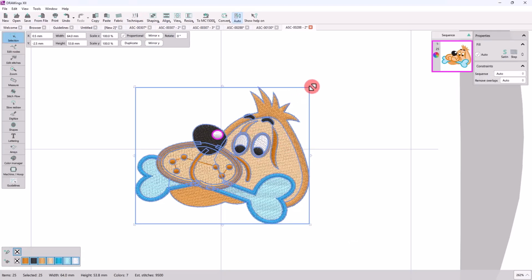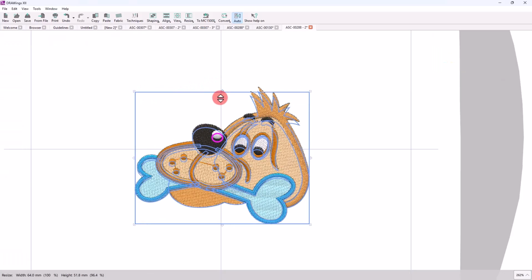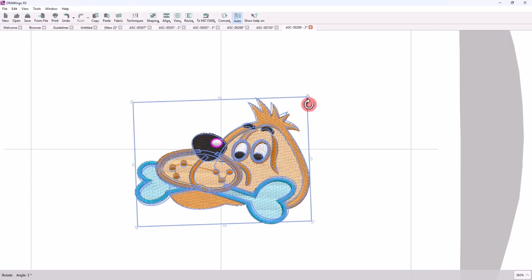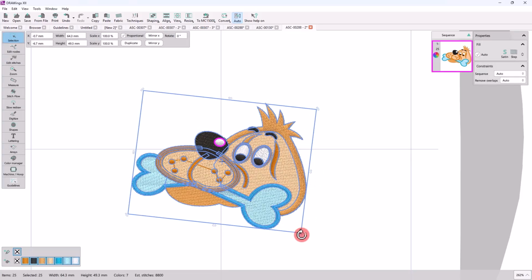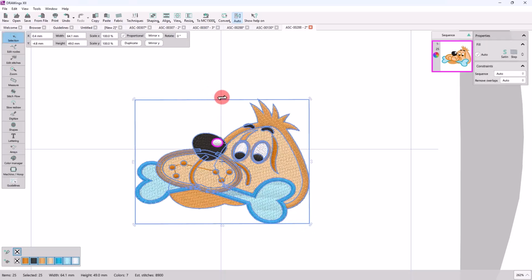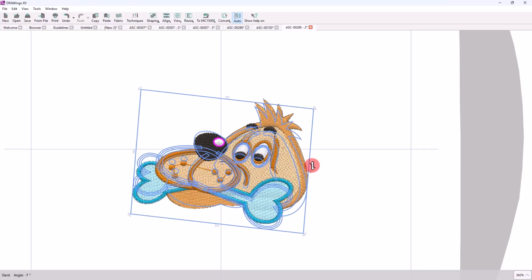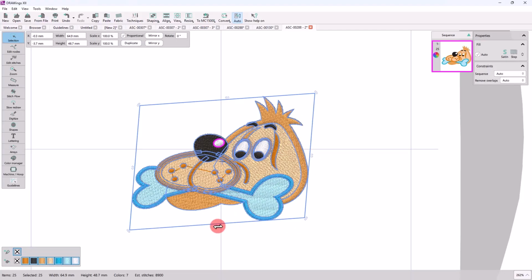Now, for any object that you select, you can see different handles over the highlighted box. Using these handles, you can only resize the selection. If you wish to rotate, instead of having to move the cursor a little to the outside of the handles, you can click on top of the selection and the corner handles switch to rotate, while the side handles switch to slant. Some users are more familiar with this way of switching between transformation modes.